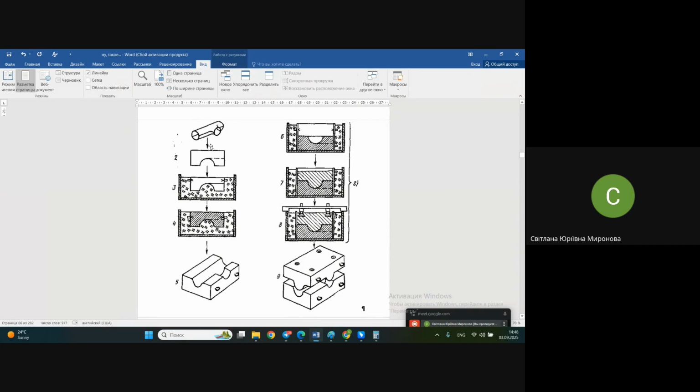Wooden mock-up. Next, from the wooden mock-up, we make a counter mock-up by molding also. Next, this thing is made by molding, by direct copying of this surface into some plastic mass, for instance. Next, it was intruded into a mixture like sand with binder, and removed, of course.